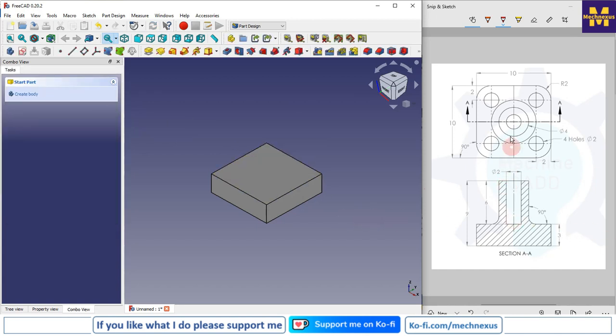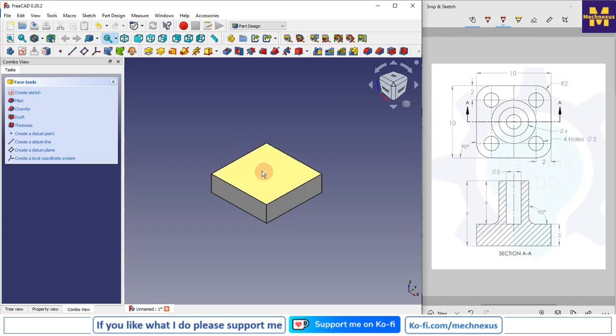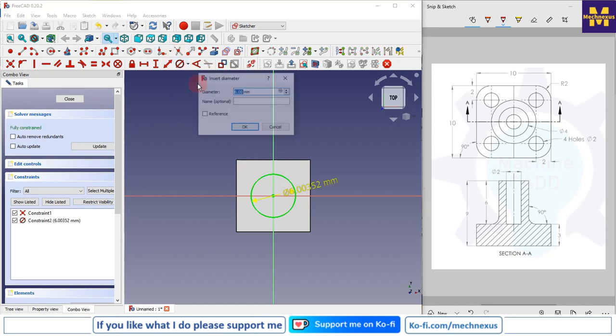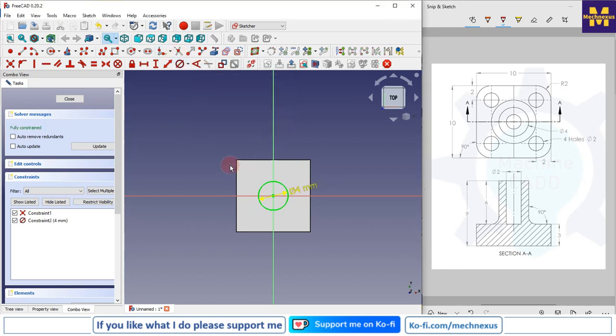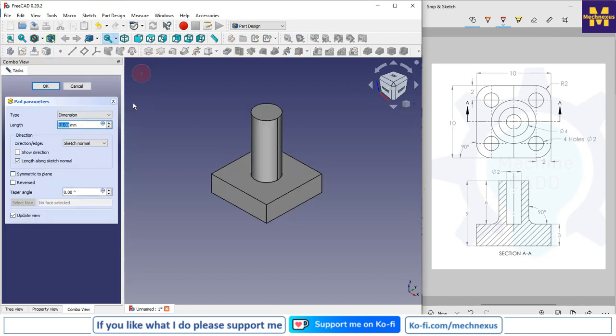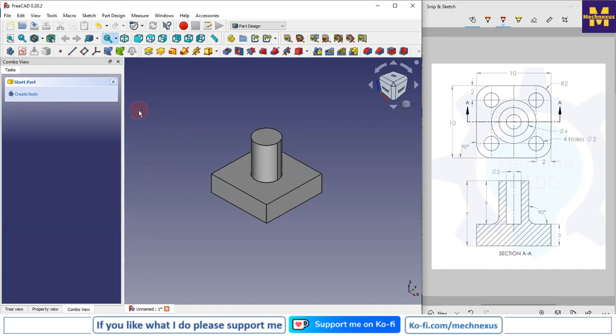And now on this face we will create a sketch and make a circle of diameter 4. So I will select the circle and give the diameter 4, and the height we can see is 6 mm. So I will come out of the sketch, and I will give the pad height 6 mm, and I will say OK.